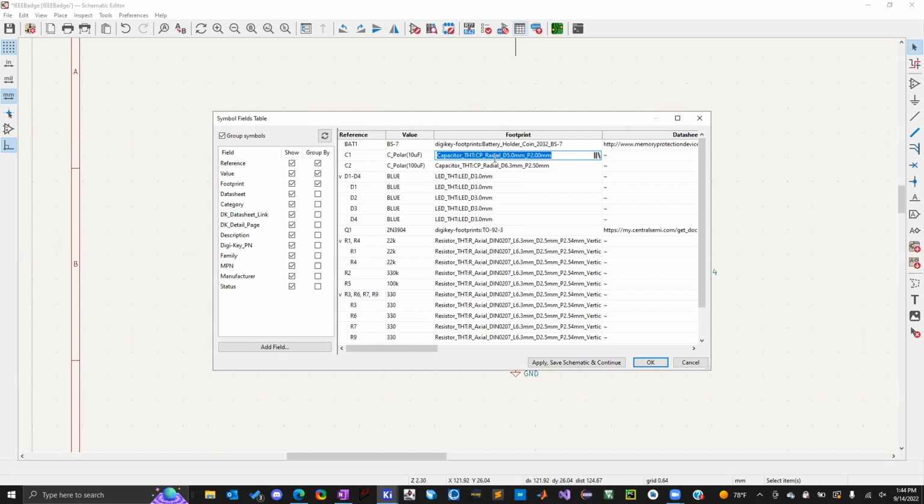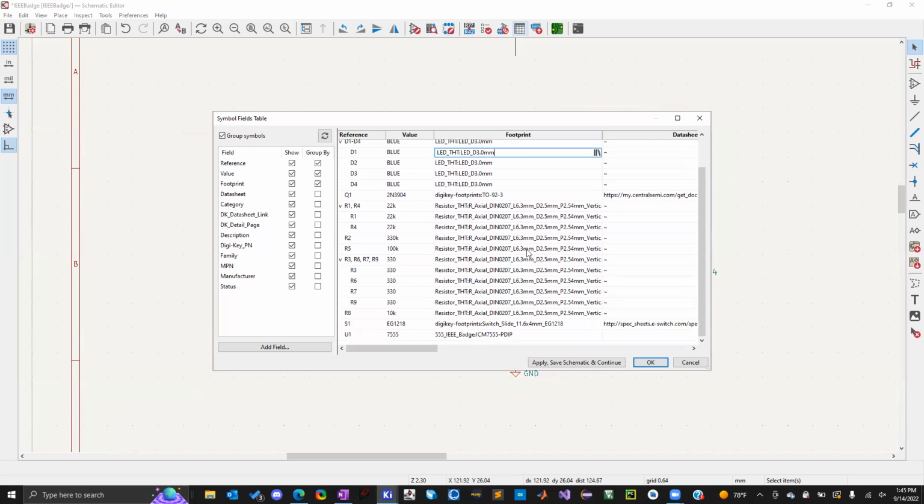You're going to learn a lot about the naming scheme of electrical components over time. There's a lot, but there's also a general idea of how you should name your components. It's common practice to put the diameter of the through holes, the pitch, which is the distance between your through holes. Here's another: diameter, pitch, diameter, length. Those are useful so that you understand, without having to look at the footprint, what the dimensions of this component are. Because these are going to be the actual components we're going to put on the circuit board.